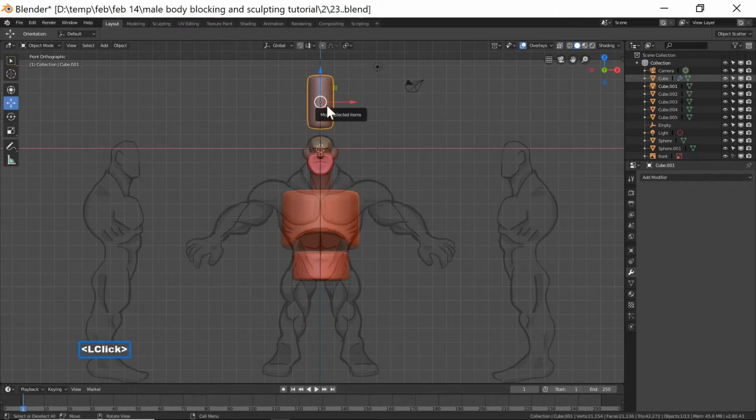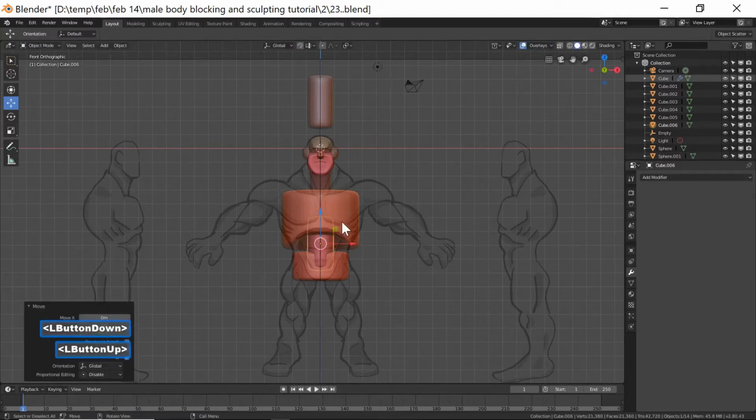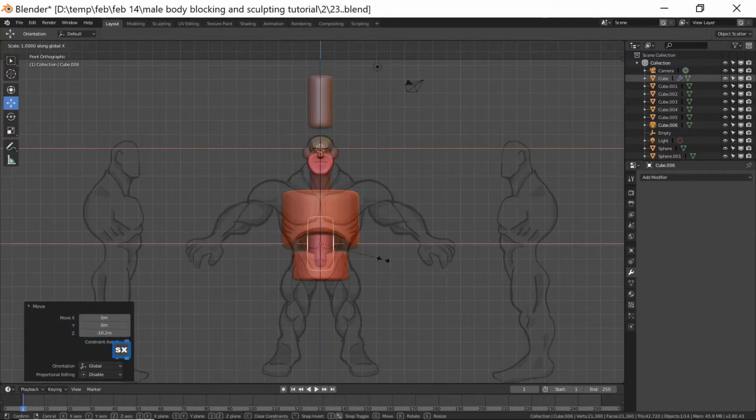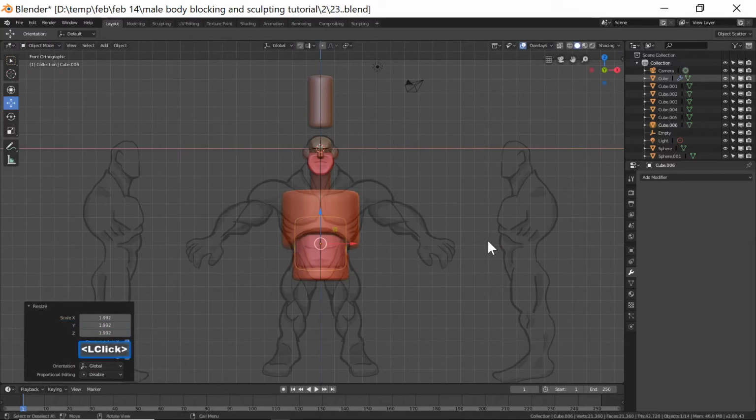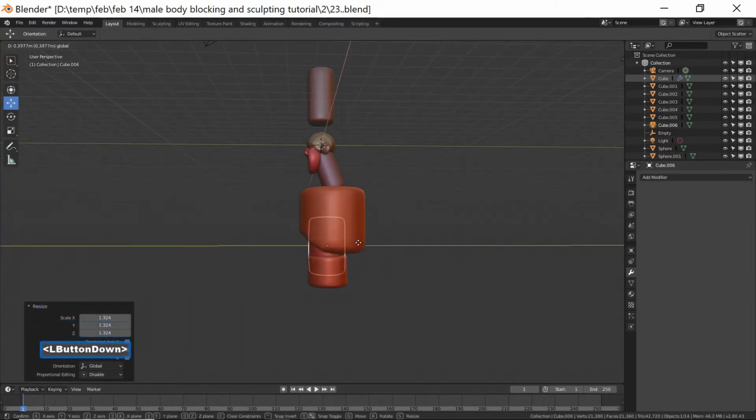I'm going to click here. Hold Shift, press D, then right click. So I duplicate it, then I right click to get that to just stay in place. Bringing this down. I press S to scale on the X axis like this. I'm going to hold the middle mouse button to rotate the view. I'm going to press S to scale on the Y axis. Pull this back.